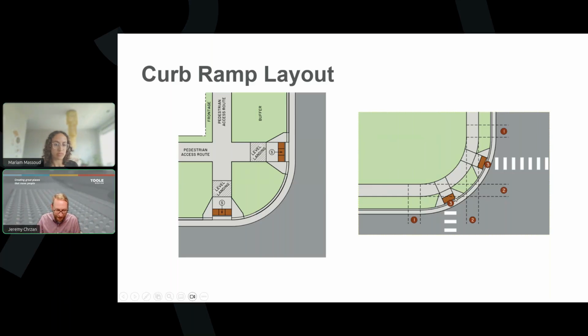And what I tend to find when this gets constructed like this with a big flare, is that pedestrians will walk over the small angle of the grass and end up killing the grass or landscaping in that area. So there is a benefit to minimizing the size of that flare when you have non-walkable area, because it will encourage pedestrians to use the paved and hardened space.